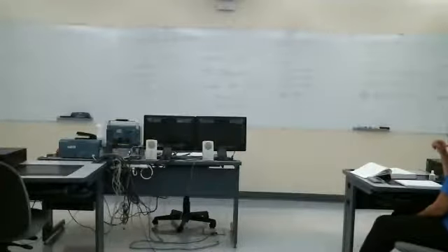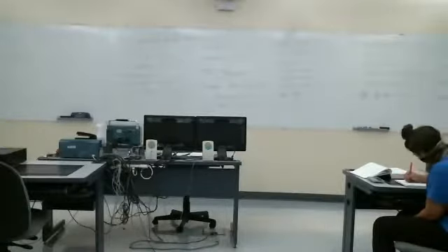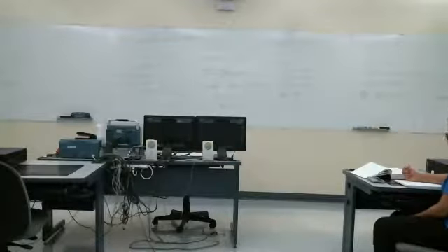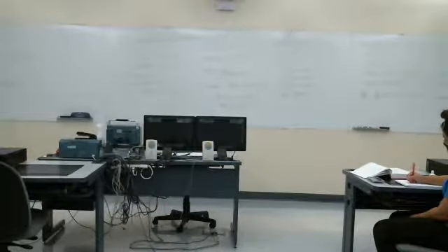I have to actually use the product rule here. This is a product of two functions of time. So I took the derivative of the first times the second. Now I've got to take the first times the derivative of the second. So this is the impulse response of the circuit. Now this simplifies a little bit.